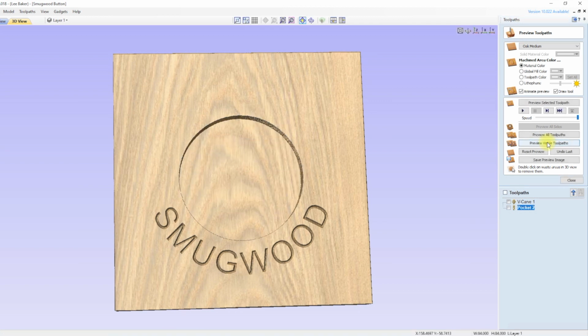Now for the ease of the video, I'm going to create just the one toolpath for the buttonholes, but when I come to actually machining it, I'll be using a slightly different method. Because I'm using a downcut spiral, when I'm drilling or removing material from such small holes, there's no place for the wood chips to go, and this can result in a number of problems.